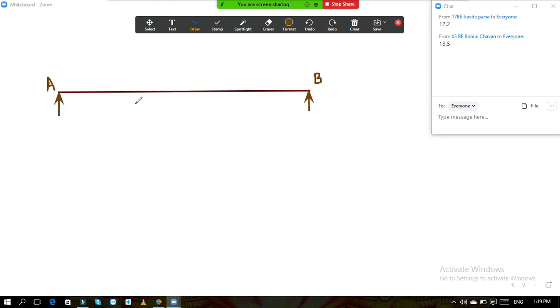You can refer to the diagram which we have drawn in the morning. And near the approach slab, that stair is there on the ground. So you will get the support reaction at that point in the approach slab, and at the landing slab we have provided the wall. So here this is your reaction RA, here is the reaction RB.